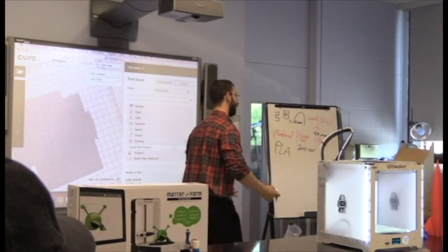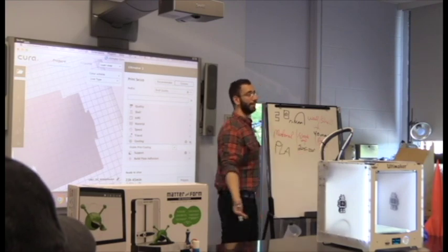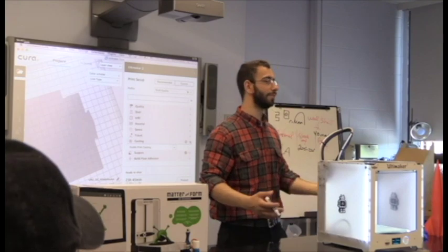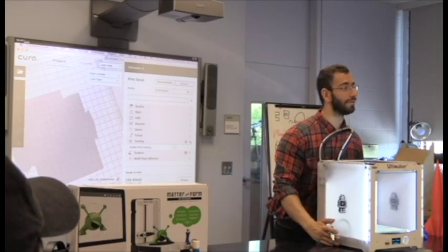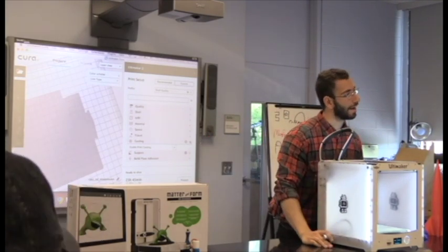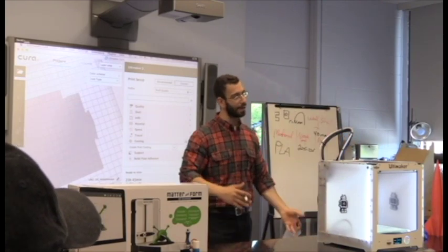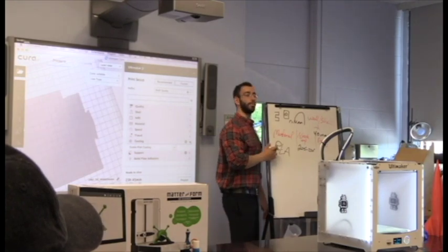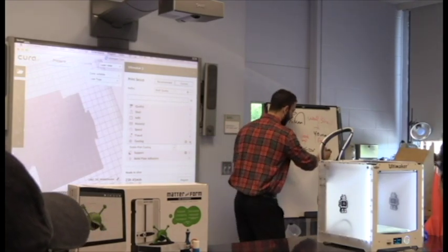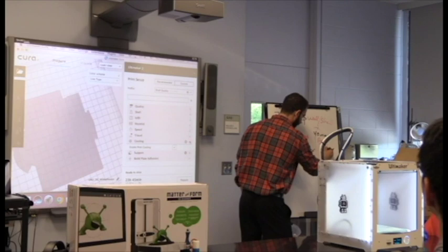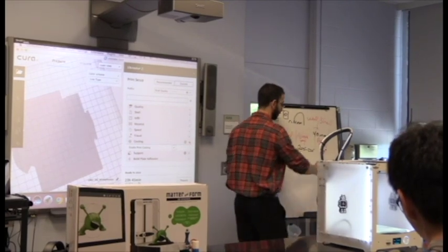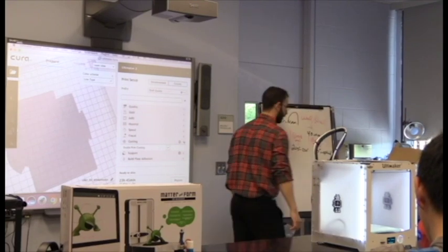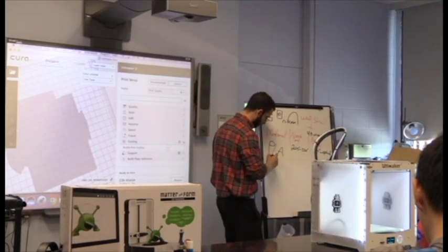Okay, the bed on PLA, you really don't need. You don't need the bed to be hot. You can. Not all printers have a heated bed. That's a nice feature to have. It's an extra thing to have. Okay, the cheaper end printers don't have a heated bed. A lot of people just print PLA, so you don't need it, but sometimes on this one, just keep it around 60. So it's kind of like a nice spot, but you don't really need it. It's optional. You don't really need that. ABS.